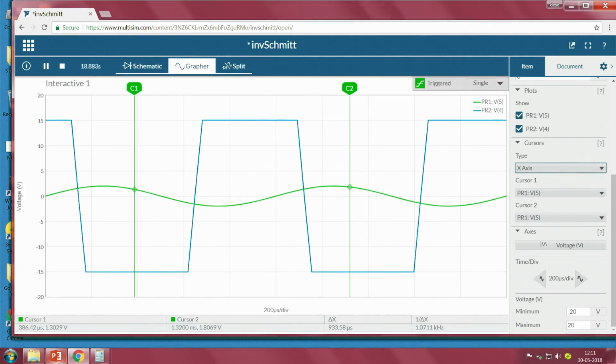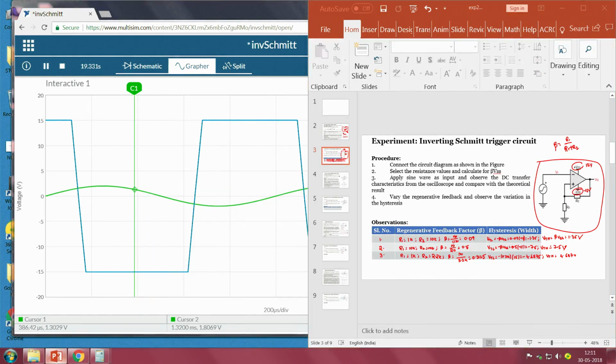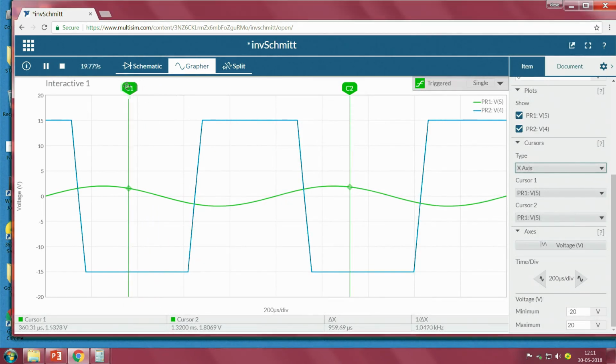When we look into the threshold values, the threshold is 1.35 volts. So, if my input is greater than 1.35, then it should go to minus VCC, isn't it? Now, slowly move towards 1.35. Somewhere close to 1.34, we can see that it is going to minus VCC. Now, another thing is, when the input is lower than minus 1.35, then the output should be plus VCC, just observe.